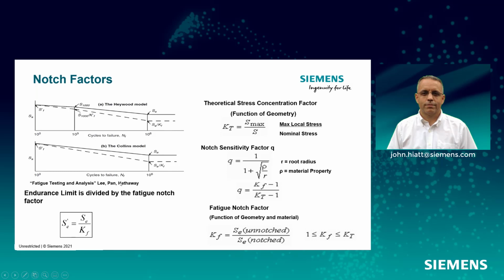There's a bibliography in here because a lot of this material, like this slide, is taken from a good durability textbook for simulation and test fatigue. If you're interested, I can send you the bibliography or the reference to it. You can see the derivation from stress concentration, but we're talking about fatigue notch factors. It's going to tell us how much we lower our SN curve. There are some ways to increase it, which have to do with surface treatments, but they're not covered here.